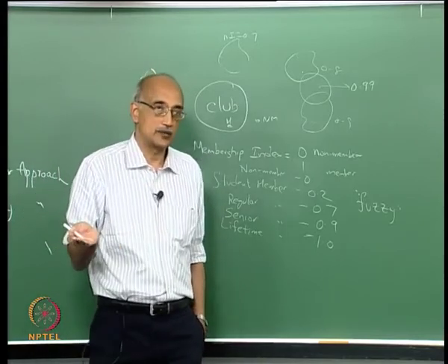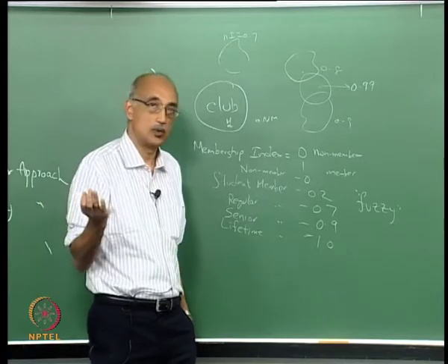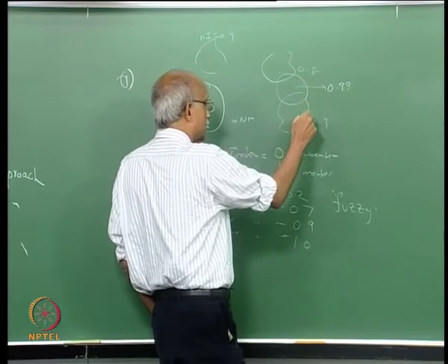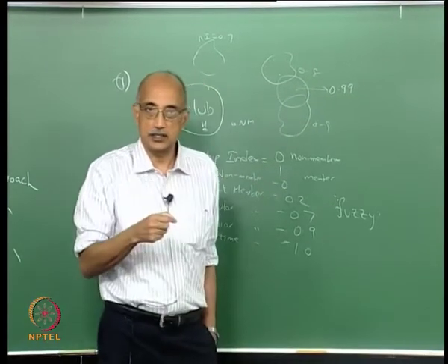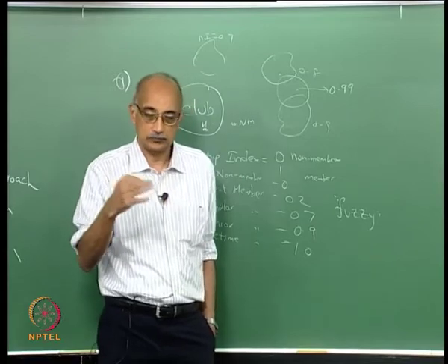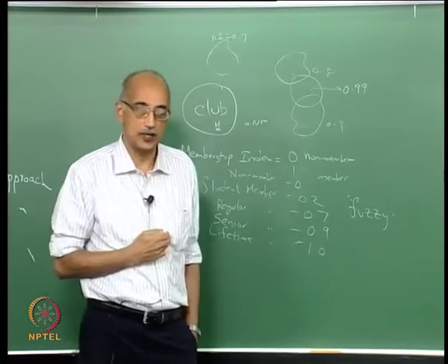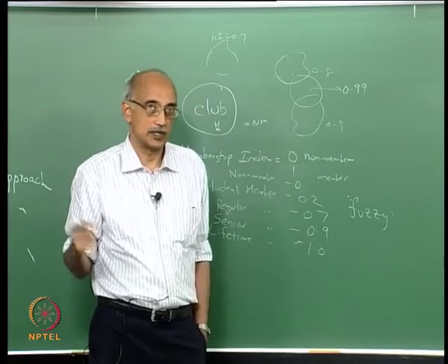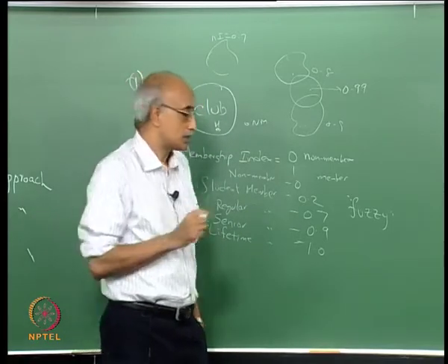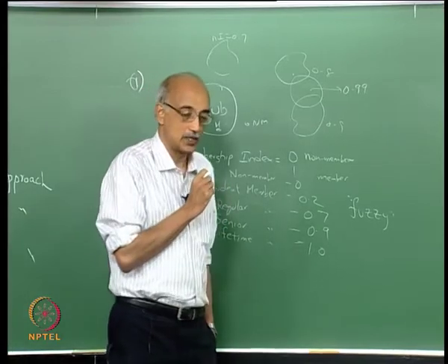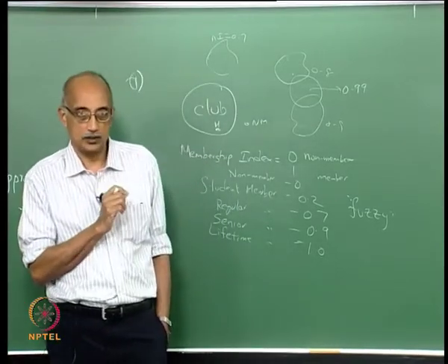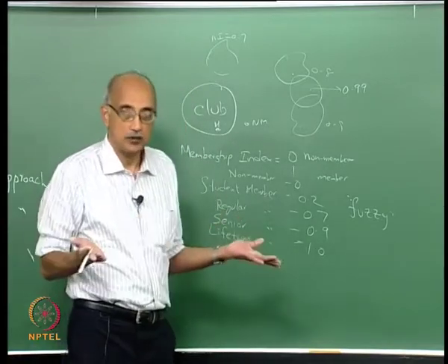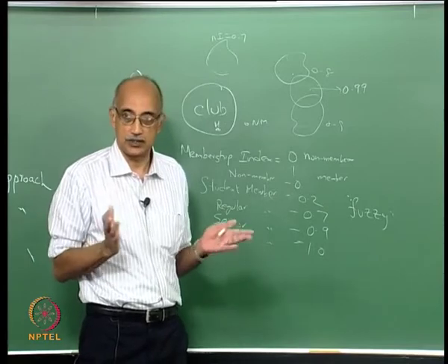If you are happy with 99% convergence, you can stop right there, or if you want better, then you compare the new set that you have generated and one of the earlier sets, and again look for cross sections between these shapes, and you keep repeating this until you get as close to 1 as you want, right. So this fuzzy membership concept is very successfully applied to particle shape characterization because by its nature particle shape is a fuzzy characteristic, okay.